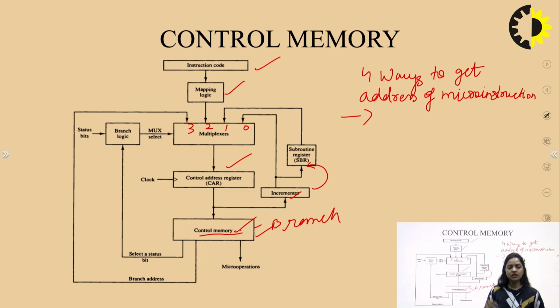So the in-between sequenced instructions are skipped. For returning back to those instructions in the sequence, we need to store that address somewhere. So we will store that address in the subroutine call register, increment the address, and get back to this position for the branching statement. And for a subroutine call, we will follow location number 1 in the multiplexer. So this is the case of branching.